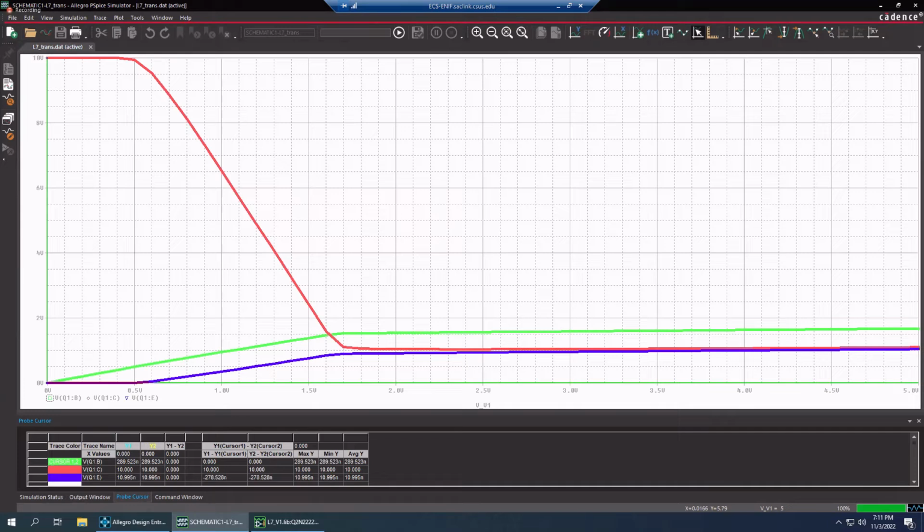And then it says on your plot, there is a region where IC is roughly equal to 0. The base emitter junction is slightly forward biased. So that's basically the cutoff that we see there. We see that the base, the green one, has some voltage across it, which would imply current, but it doesn't turn on until we get to a certain threshold. So that's in cutoff. So that's just a detail.